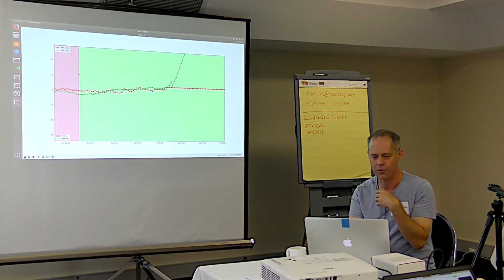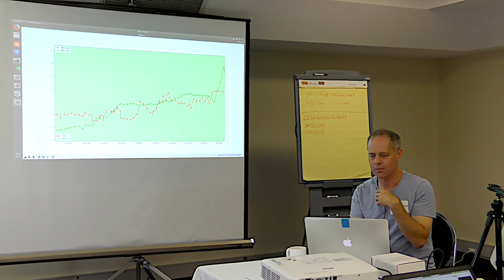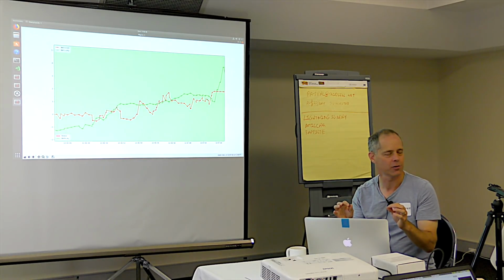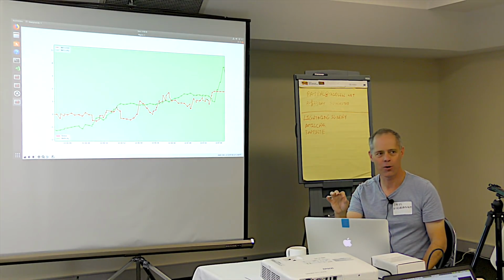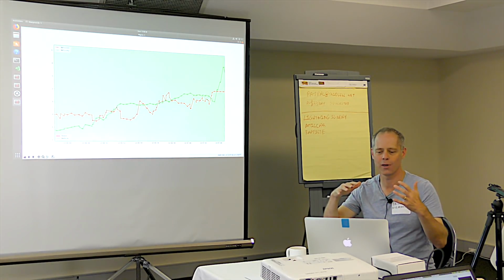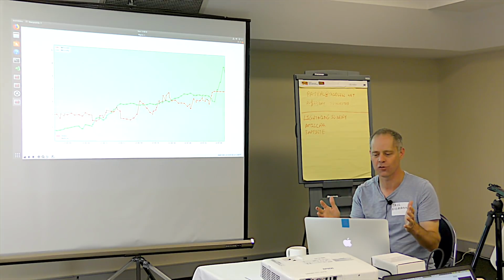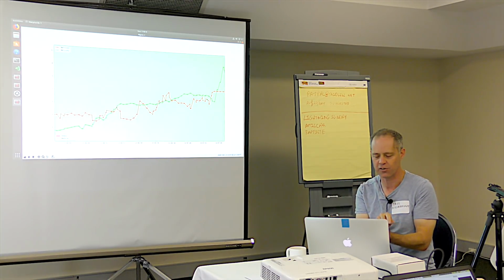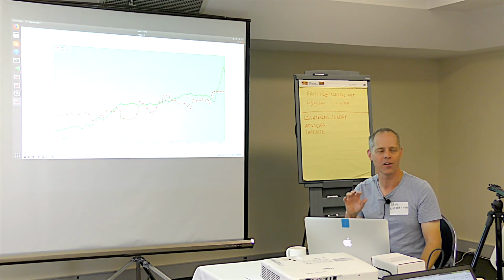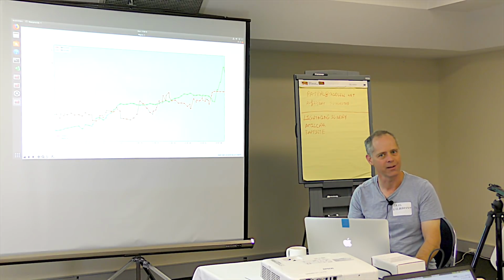What's happening before it diverges is you'll see that both the vertical velocity innovation and the vertical position innovation are positive. When you see they're positive and the EKF goes into an uncontrollable state, it basically starts rejecting the GPS velocity, it starts rejecting the baro, and these innovations are positive. That is nearly always, like 99% of the time, clipping. Okay.